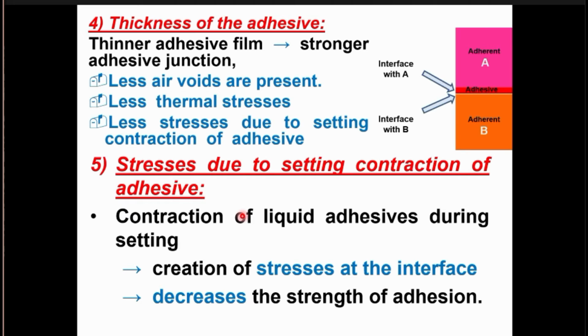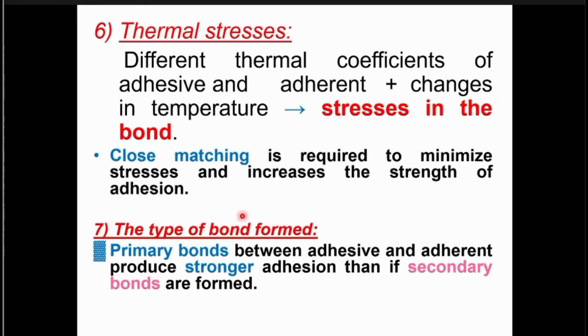Otherwise, we will be facing stresses due to setting contraction. Because during the setting, the adhesive will contract and put stresses on the interface. If we are using more material, thick adhesive, we will face more stresses at the interface. So which means it might fail the bond later on.